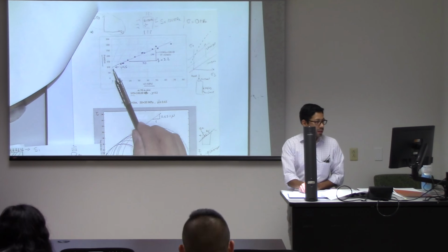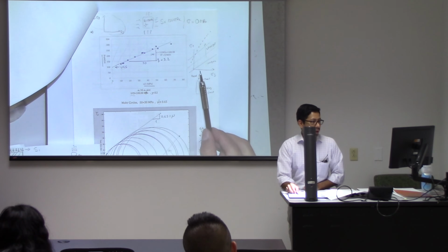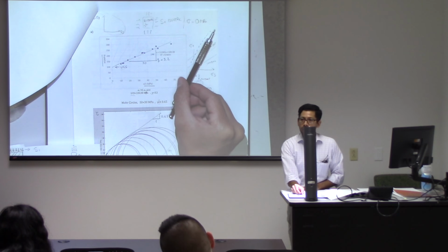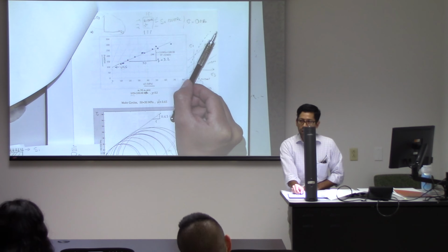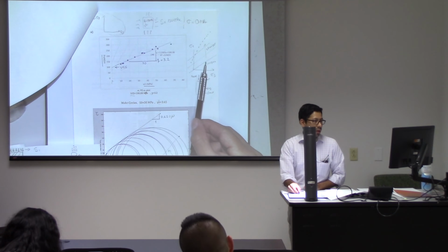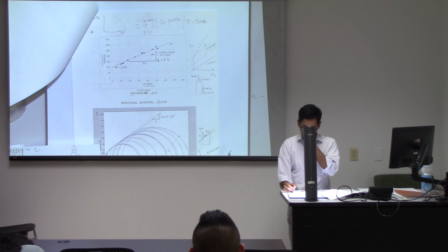Conceptually, what does this line mean? Well, it tells you the strength of the rock. The lower the line, the less cementation it has. The steeper the line, the more frictional strength it has. So this is a weak, uncemented rock, and as you increase in this direction, it gets stronger.